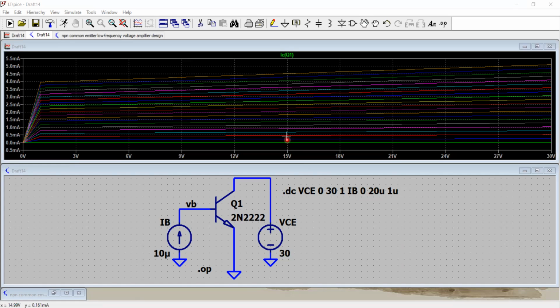And then from this 15, I am given the IC to be chosen as 2 milliampere. So right here, 2 milliampere. So I go here, and somewhere here, I will have that Q point, right? So my Q point here will be IC equal to 2 milliampere, and the voltage at the collector of the transistor with respect to emitter, where emitter is ground, is 15 volts.